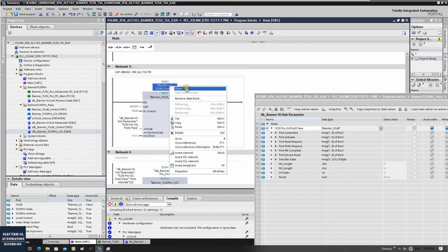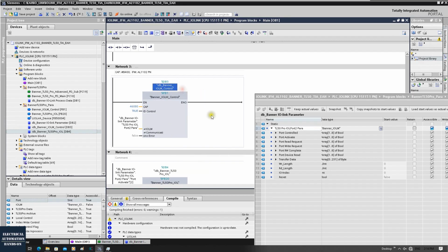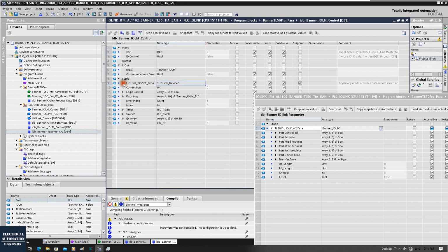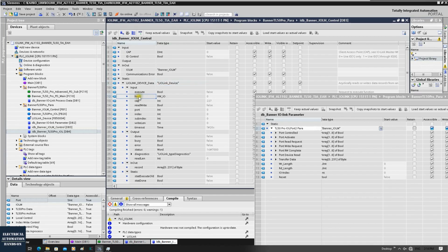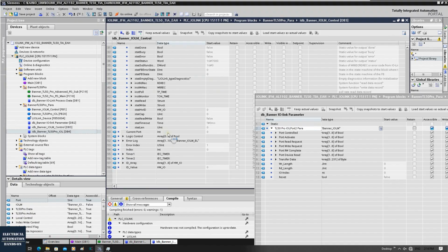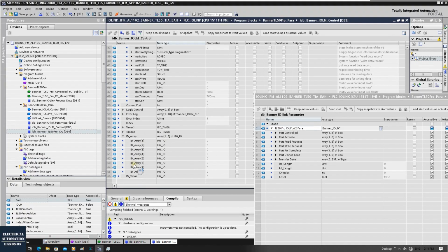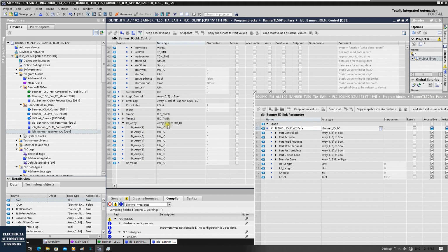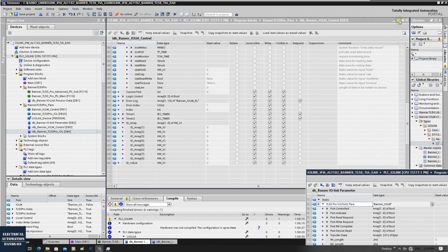Now if we open this instance DB, this is a Siemens function block, and for this hardware ID, we need to set this value. This function block prepared this hardware ID list, and it is located here, this ID array. It's very hidden, it's not quite great. A new user will maybe ignore these things, so that's why I like to demonstrate this. Now let's float it,